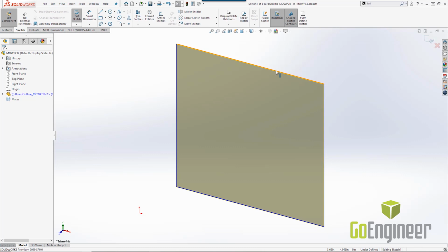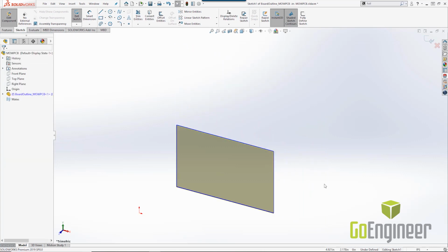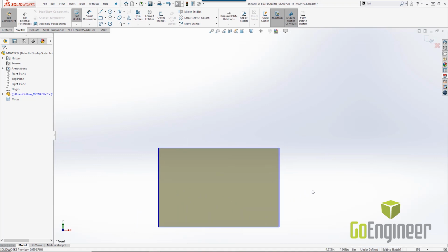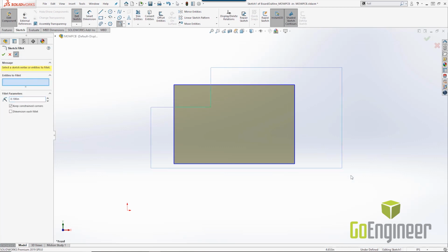And we're presented with a basic board, and here I'm just going to make a couple adjustments. Nothing spectacularly new, but a few things that I want to share with you here. I won't say it's frustrating, but as a SolidWorks user, I like dimensions. So I'm going to add a couple things here. We're going to round off the corners and add some dimensions to the board. So to round off those corners, we're just going to highlight the four edges, tell it we'd like these to be 0.25, hit the checkbox, and let it go from there.